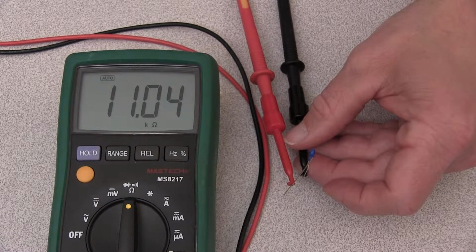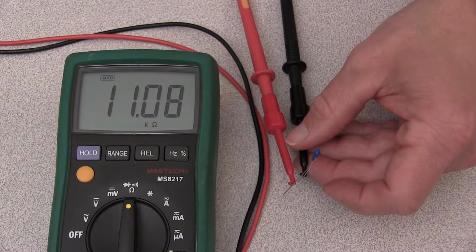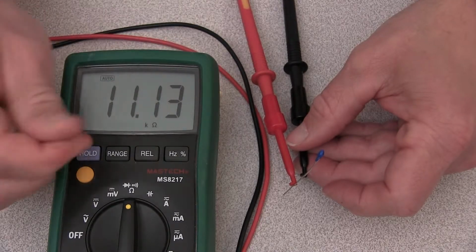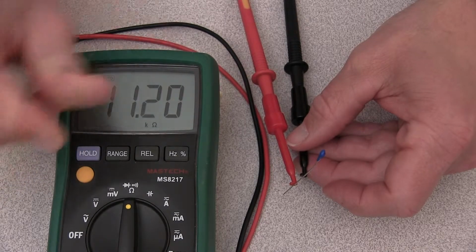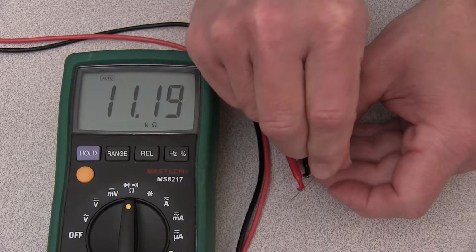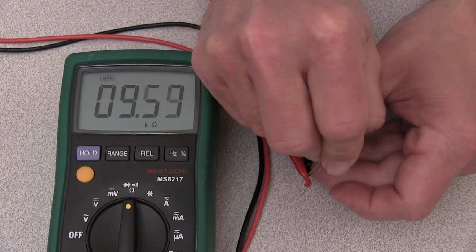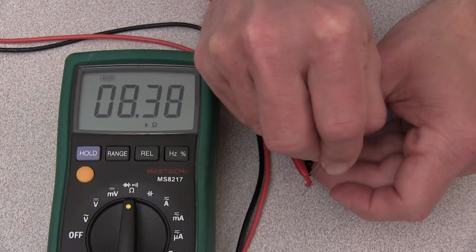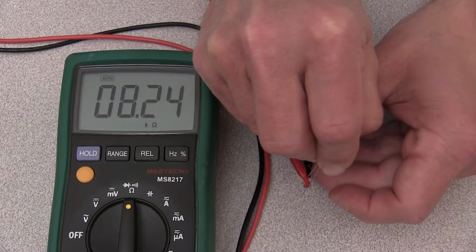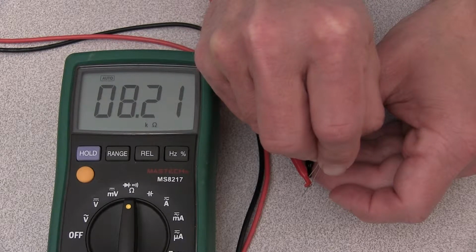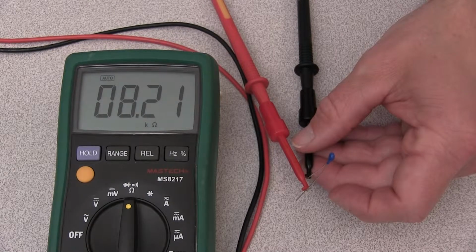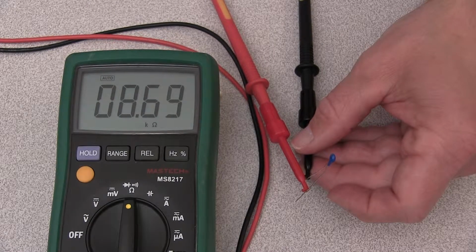When the thermistor is at room temperature, the resistance is about 11 kiloohms. If I warm my fingers a little bit and then pinch the thermistor to warm it, I get a resistance of a little over 8 kiloohms. Notice that the temperature measurements tend to be relatively slow. It takes a while to warm something up or cool it down, so you may have to be a little patient with this lab and allow the system some time to respond.